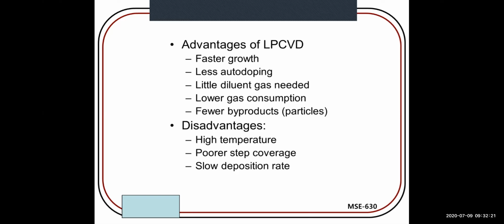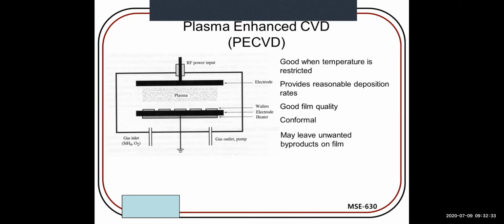Disadvantages are the high temperature required to carry out this deposition. Poorer step coverage, because step coverage is not very good. Slow deposition rate. The deposition rate is very slow and it takes a lot of time for the deposition of thin film.